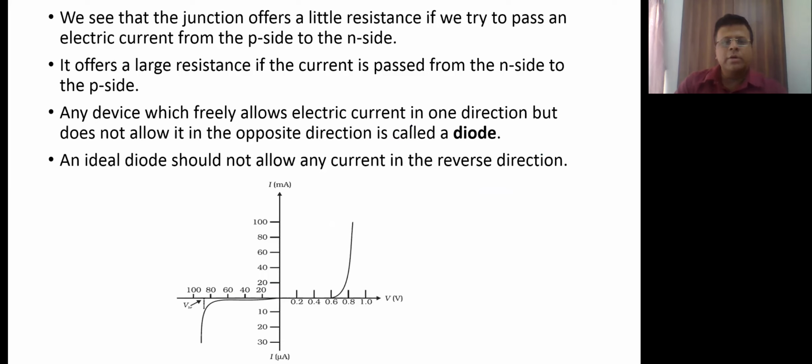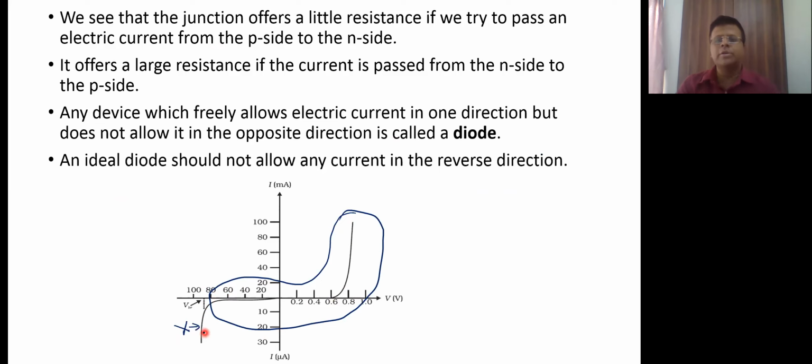So why do we call the PN junction a diode? We are writing it here. As you can see in this VI characteristic, when the diode is forward biased, see, PN junction is generally used in this region, as I already told you before. It is not used in this region unless it is planned to be used as a voltage regulator.